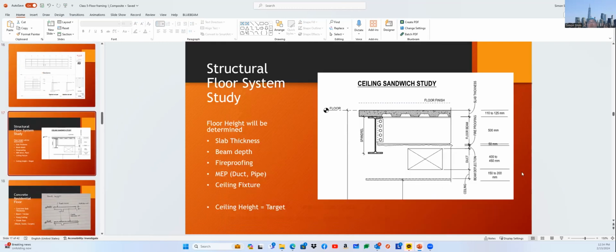All right, what we are focusing on now is that we're about to design the floor framing and beam size. First of all, the layout of the column grid sets all your floor framing geometry, and we need to define the floor design load so that we can design the floor framing. But it's not just pure steel. The reason is composite floor framing, which we need to understand. We're going to study it a little bit.